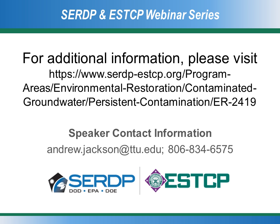Great, thank you. Do your hydraulic data represent a snapshot in time, or can you also track changes over time? For a single deployment, you're looking at an average of the velocity over that time period. So if you want to look at changes over time, you would have to do multiple deployments. You'd put samplers in, wait 2 or 3 days, put some more samplers in, wait 2 or 3 more days, put some more in, and then pull them out. Because each sampler deployment is an average of the velocity over the deployment time.